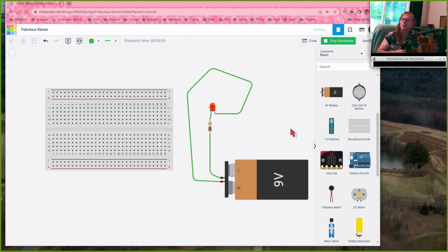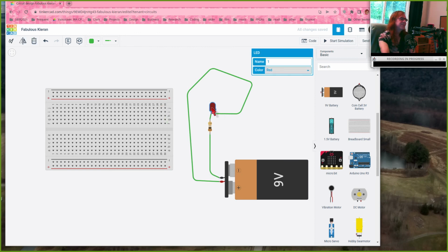Right, so think back to 120. When you use a LED, you have to put a resistor in series with it to limit the current. We'll be talking about that more in the coming classes. But you know, you can place these components in the protoboard and make connectivity. Once you discover the connectivity, and again, there's a little cheat. If I hover over one of these circles, Tinkercad will show me which circles are connected to it. So experiment 2 is kind of done for you by Tinkercad.